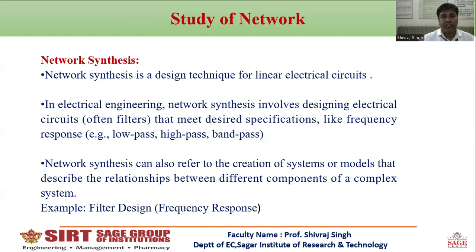In electrical engineering, network synthesis involves designing the electrical circuit for desired specifications like frequency response, like low pass filter, high pass filter, band pass filter, band reject filter, and so on. Network synthesis can also refer to creating a system or model that describes the relation between the different components of a complex system.